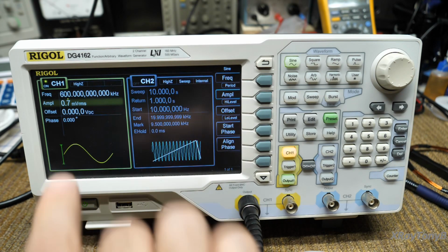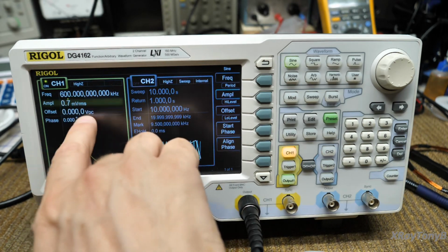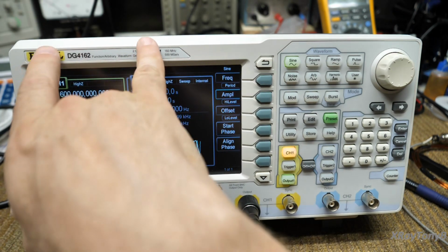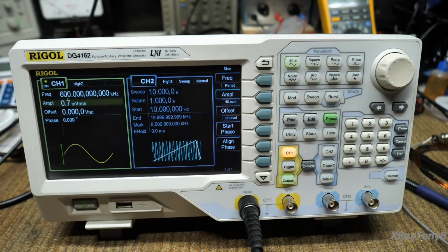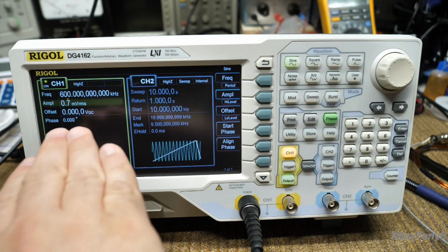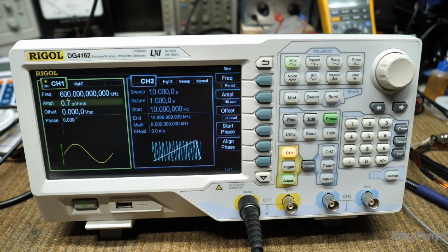And even at that level, you're right at the edge of what this thing can do, so the accuracy is not going to be perfect. So most waveform generators like this, these function generators, are not designed to generate a radio amplitude signal. The output is too high. So in other words, for that to work, you have to be able to attenuate this even smaller.